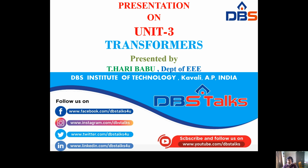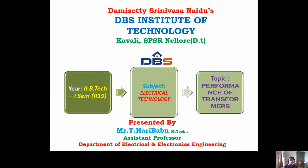That will give some numerical values. Based on those numerical values, we have to decide whether the particular transformer is working efficiently or not, right? So we go to the topic, that is the performance of a transformer, which is nothing but transformer tests. Two tests are done on the transformer: open circuit test or no load test, and short circuit test or impedance test.